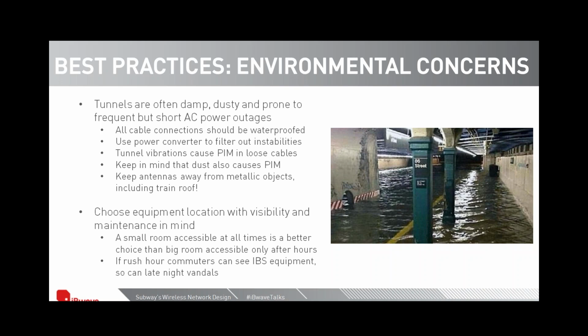Keep in mind that tunnel vibrations cause PIM in loose cables, so cables can be loose in tunnels, and dust also causes PIM. Most importantly, metallic objects cause PIM, so antennas should be kept away from metallic objects at the station, but also away from the train roof. If you are designing in a tunnel, do not put the antenna on the top. Do not put it in a ceiling, because the incoming train will cause PIM.